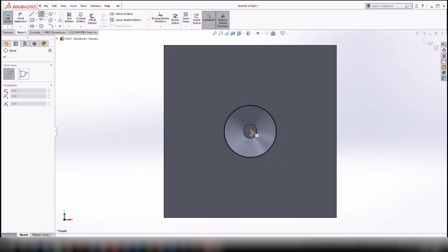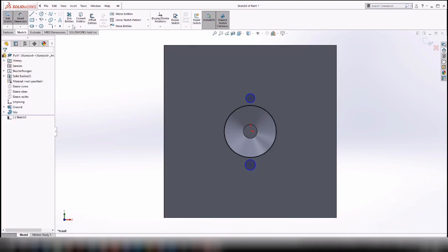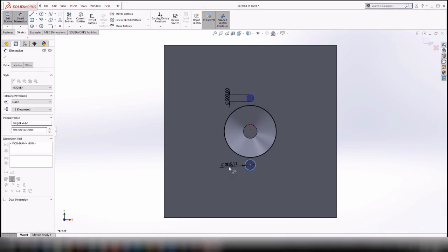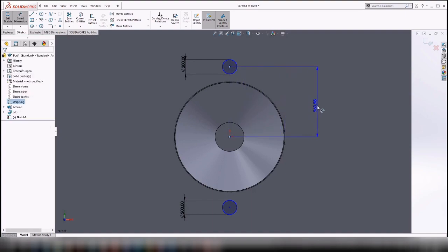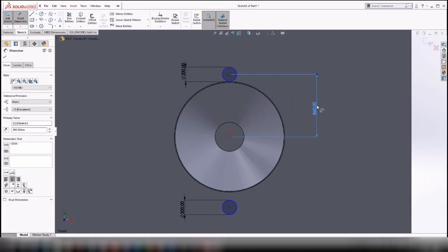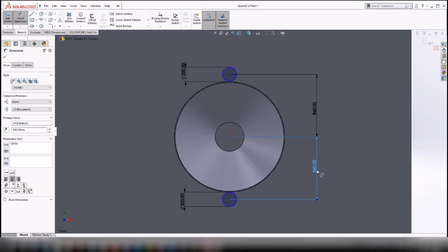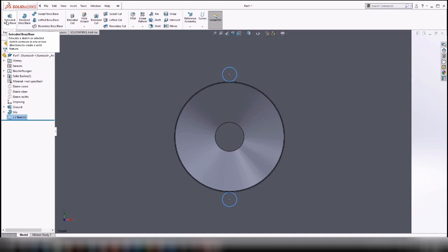Next we add the frame. We look normal to the ground and draw two circles with a radius of 100 mm. Now we set the distance to the origin to 860. We know the radius of the silo is 750 mm, the wall thickness is 10 mm and the radius of the frame is 100 mm. Hence, the frame will contact the silo on the outer wall.